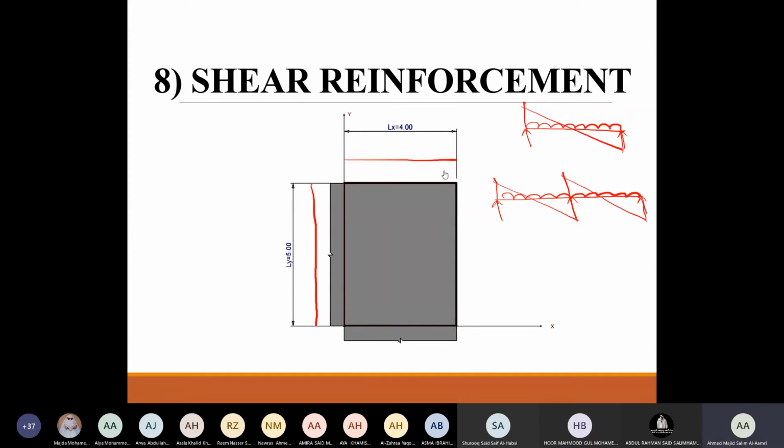Shear force does not change when it comes to the type of support, whether it's continuous or discontinuous. Is it clear? For bending moment, it will change whether the value is going to be 0 or more than 0. Now, when it comes to shear force, it's a reaction. It's a vertical reaction. So it's going to be there whether it's continuous or non-continuous. Are we clear?